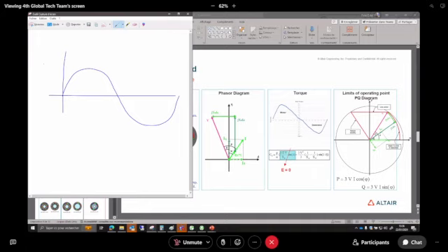And if there are inserted magnets, we will have what we call the reluctance torque, which is the interaction between the magnetic field on the stator and the reluctance on the rotor. And we will have the cogging torque, which is the interaction between the magnets and the stator slots. Here, for the synchronous reluctance machine, there are no magnets on the rotor, so this torque is not produced.